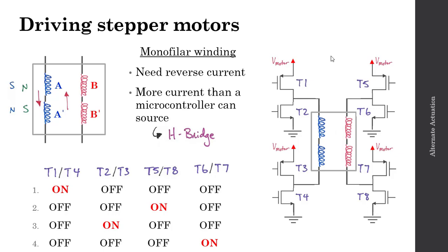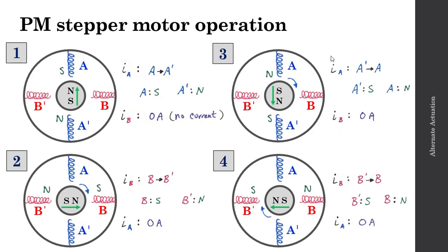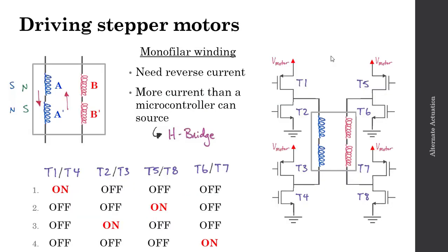So this allows us to achieve this stepper motor operation that we had previously explored, in this case 4 steps for a 2-phase motor, by using a dual H-bridge circuit. In terms of complexity, obviously if you have more phases or more poles in an attempt to get even finer step increments, the circuitry complexity increases dramatically.